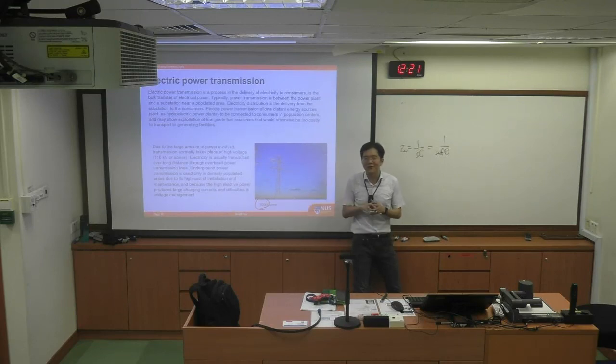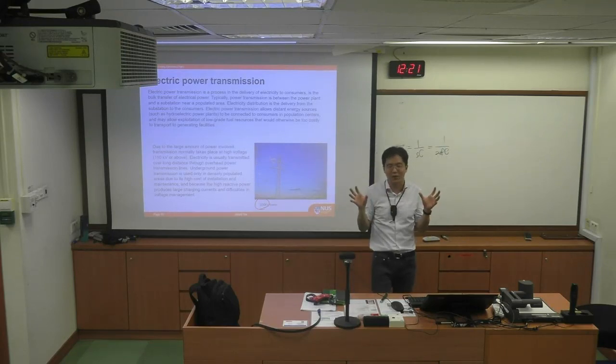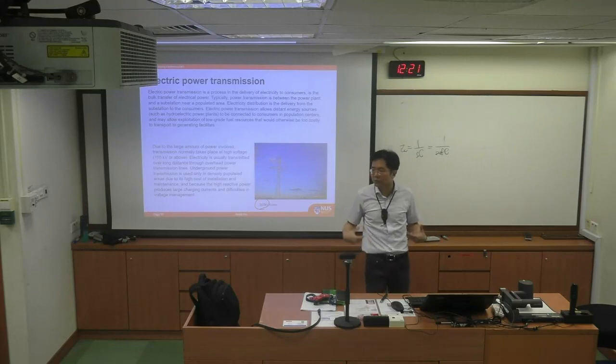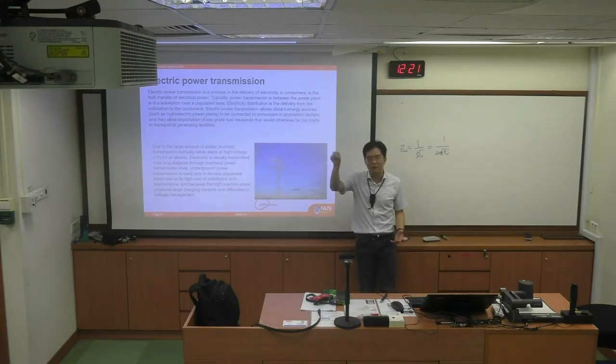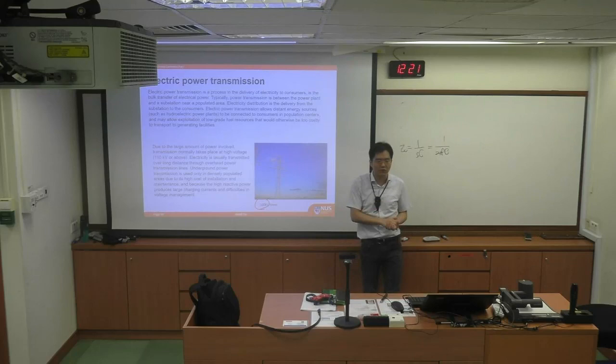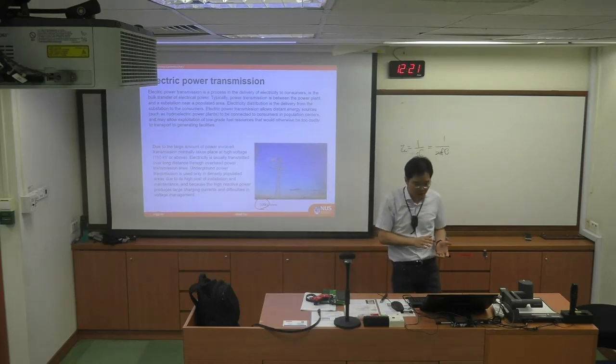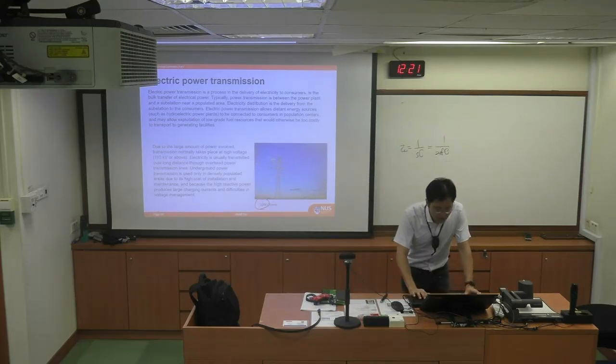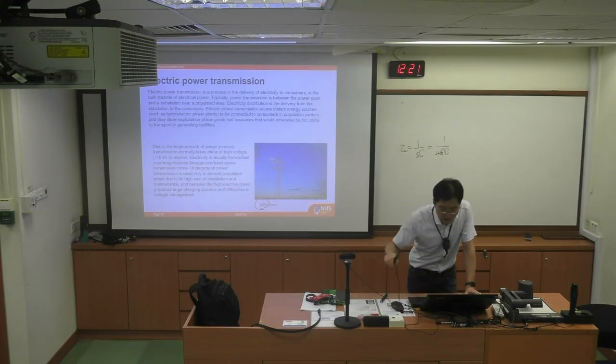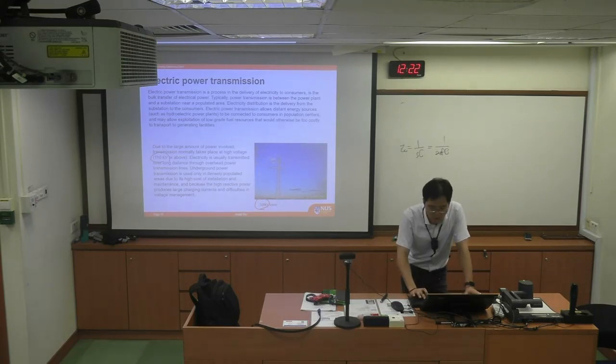So you don't ever touch a 10 kilovolt or higher power line, even if you have a perfect insulating glove with perfect insulating shoes, you don't even attempt that because you will still have considerable amount of current flowing through your body. That's very dangerous. Now, anyways, this transmission of high power will be involving elevating the voltage to a higher level.